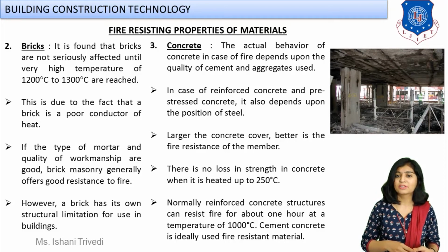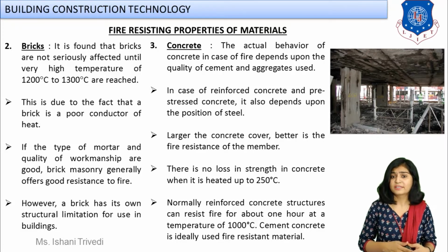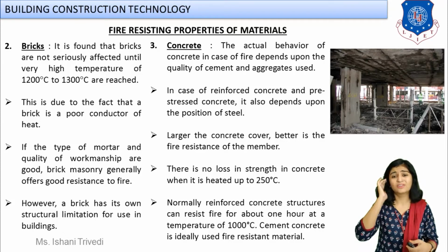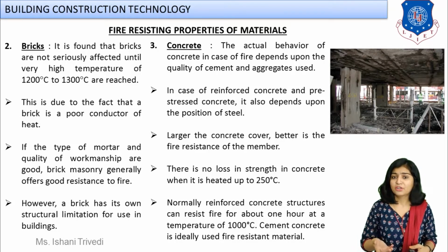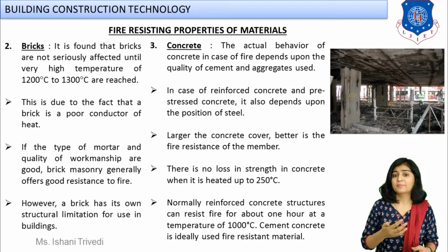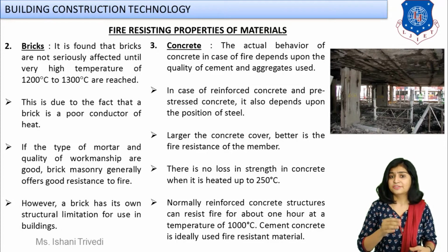Next, we are discussing the third material, concrete. Now, students, you know concrete very well, I don't need to go into that depth. Concrete has a very good fire-resisting property. There is no loss in strength. Concrete remains unaffected when it is heated up to 250 degrees Celsius. Later on there will be damage, there will be a burning process, but it will be slower. Sometimes lime mortar can burn easily, but the concrete material will be safe from fire, and generally in RCC buildings you can escape from the building easily when it is made of concrete.